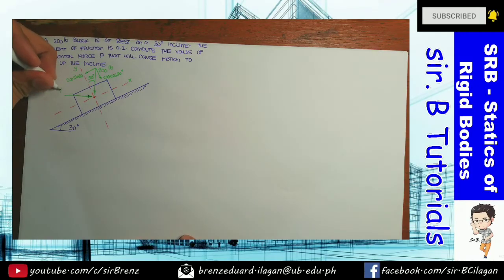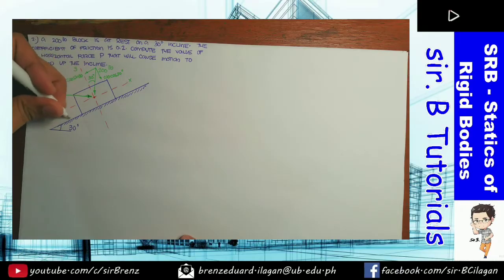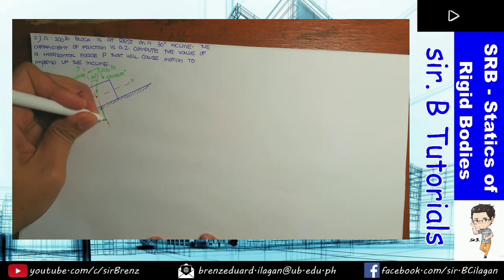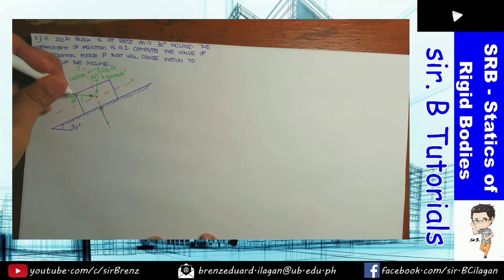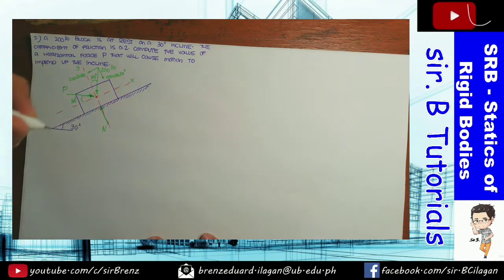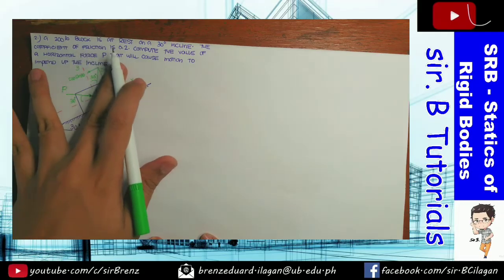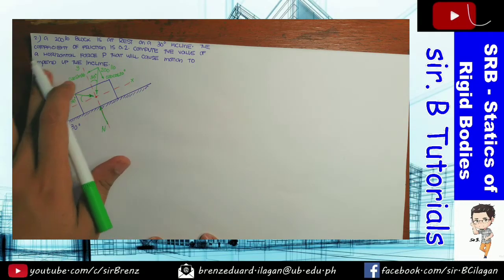So if this is your P, and this is 30 degrees, this is also equal to 30 degrees. And the rest is the same. Here you have the normal force, or the normal pressure exerted by the block. So that is N. And it says to compute the horizontal force P that will cause the motion to impend up the incline.